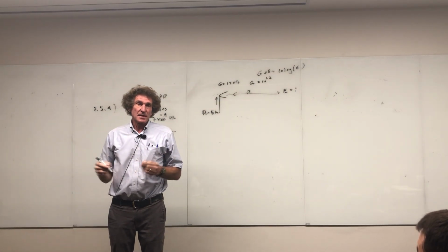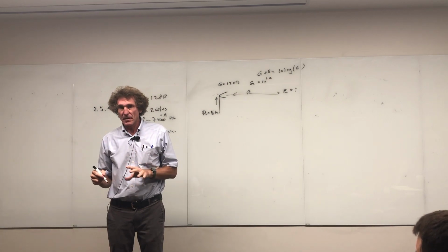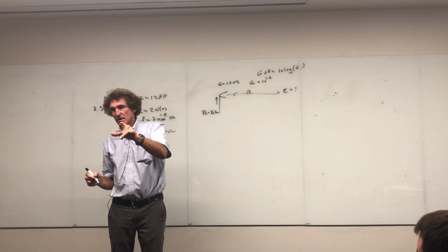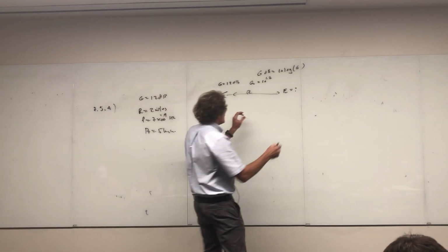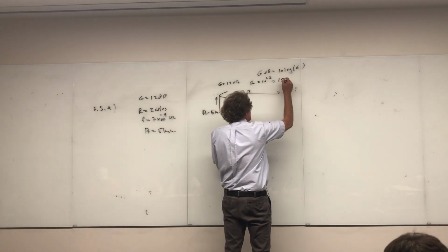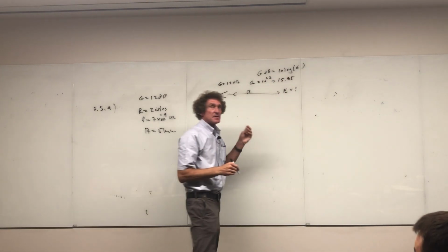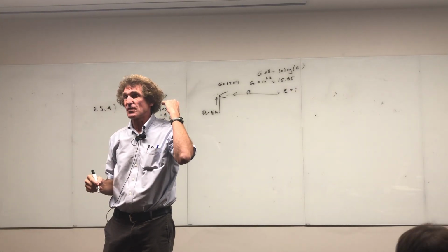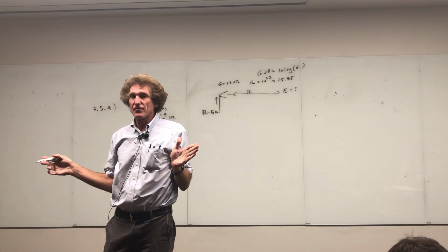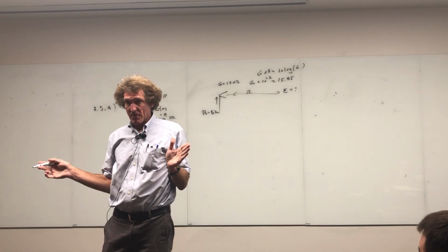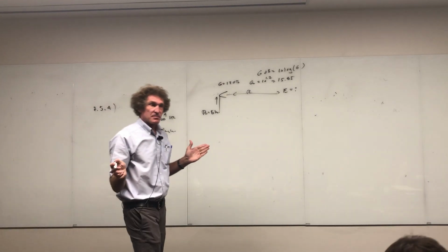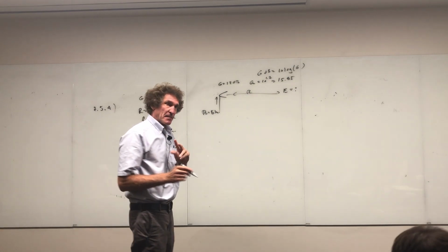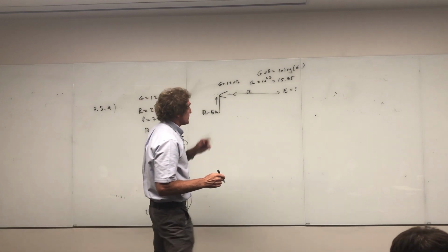Now, I don't know exactly what that number is. Probably around 15. I'm not sure. You can check. 15.85. All right, so that's 15.85. Contrast that to the gain of a half-wave dipole, 1.64. It's much, much greater. This is focusing power. It's not super focused, but it's focusing power. And I'll show you a way to figure out the actual beam width from this in a bit, but for now, it's a fair amount of focus.